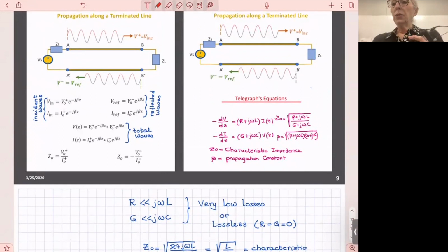So you don't see R times delta Z or something. These are not total resistances or total inductances. These are still per unit length. So when we write the equations to characterize one infinitesimally short transmission line, they apply to the whole transmission line. And in these equations here, R is per unit length, L is per unit length, G is per unit length, and C. Eventually all of these delta Z's that we had multiplied by that, they all went here.